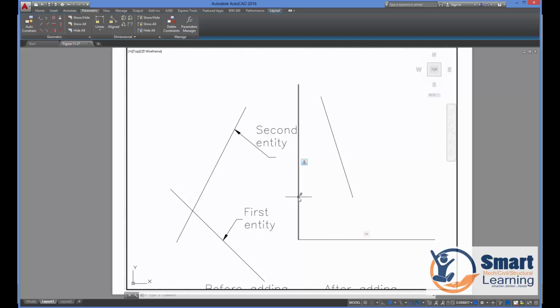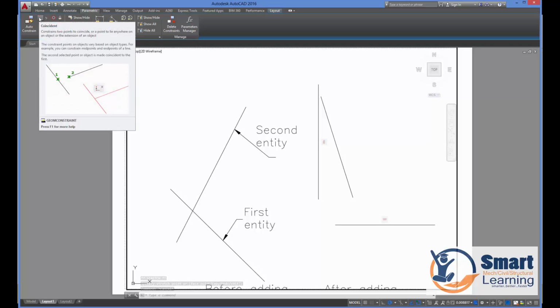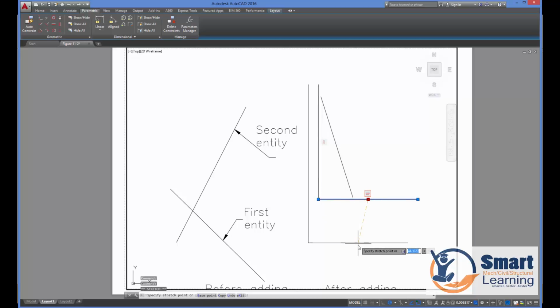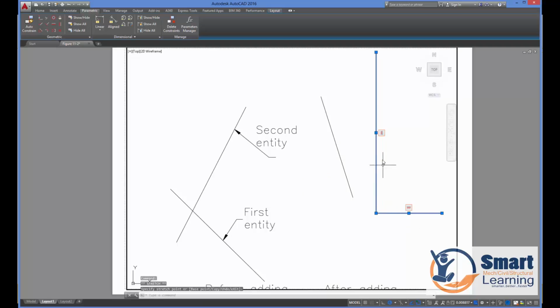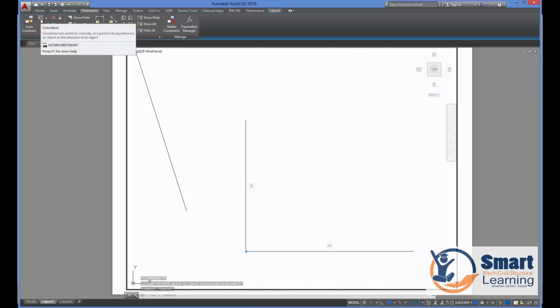And another thing I'll show you here is, if you see this end I can move it, and this end also I can move independently. But if you look at this particular constraint, which I personally use most of the time, and you click this particular end, this red highlighted, and this end, what happens is these two are now integrated at that point, and when you try to move this, the whole object is going to move, irrespective of the type of the height or whatever you talk about. So here you can lock this particular location by assigning this coincident.